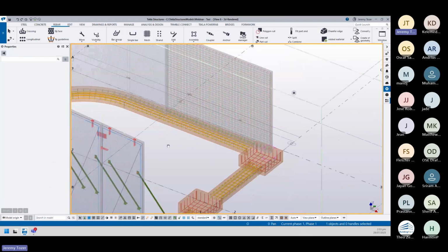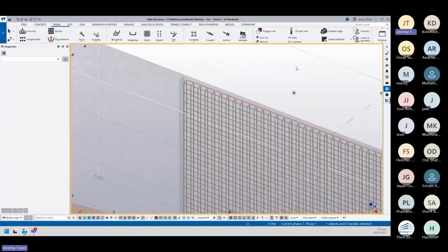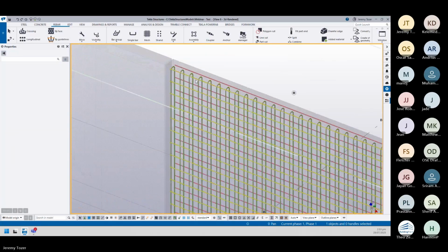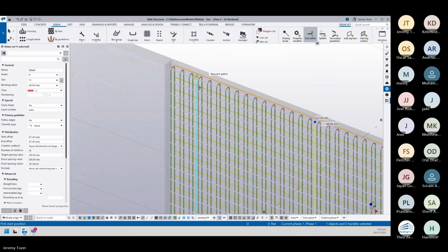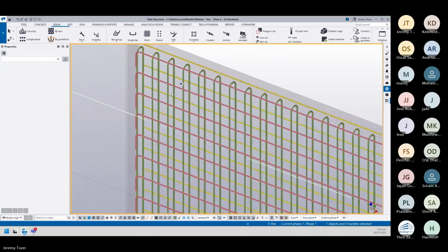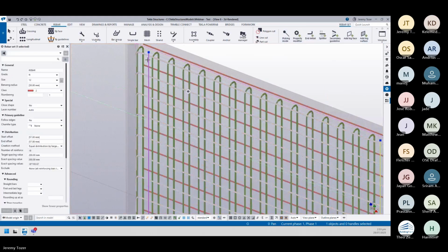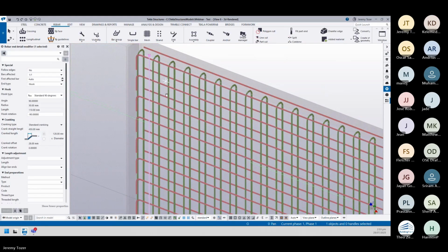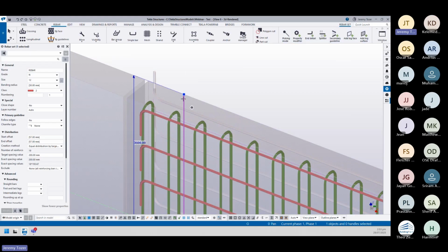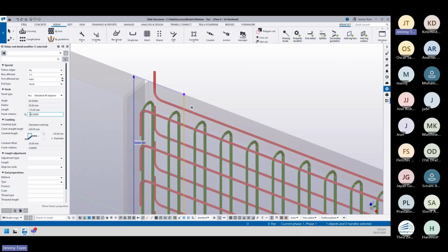One thing I normally do when I'm doing panels, I'll put these other returns in. It remembers your last settings. Copy that modifier from there to there, then select that modifier and take the minus off.